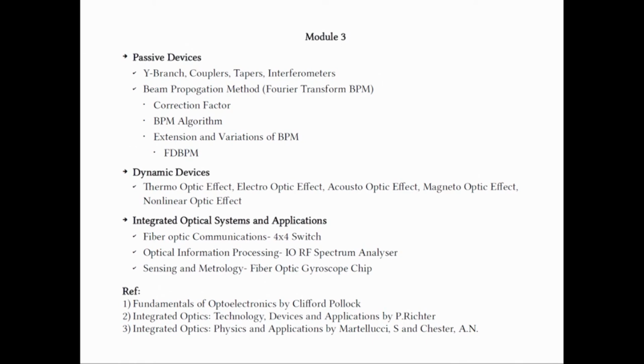So, a typical spectrum analyzer will consist of an acousto-optic cell or the IDT pattern, which will create a grating on the chip, and we have noted that integrated optical lenses are used for focusing and defocusing, where the functioning can be analogous to that of bulk lenses. We have not considered the integrated optical lenses in this particular course, and from the references given at the end, you can look at the properties and see what are the differences between the lenses in bulk and integrated. So, in this RF spectrum analyzer, we have the RF field applied to the IDT pattern and optical fields